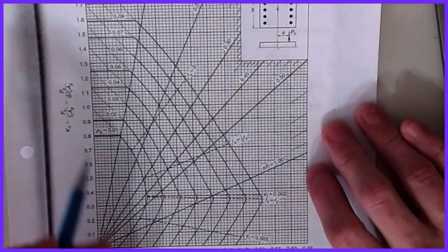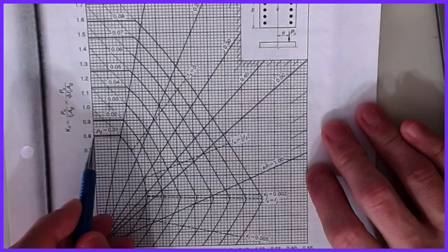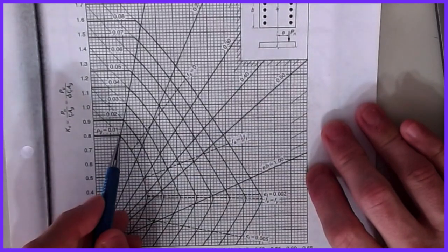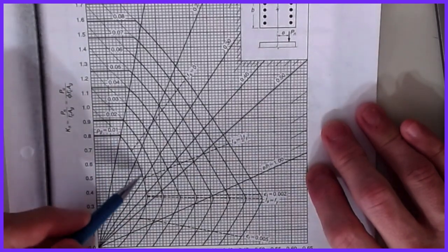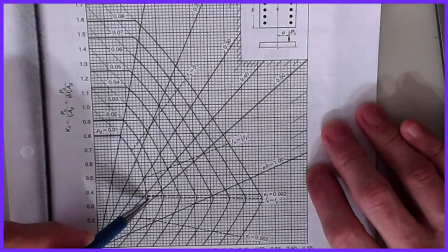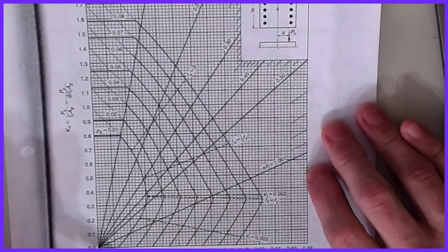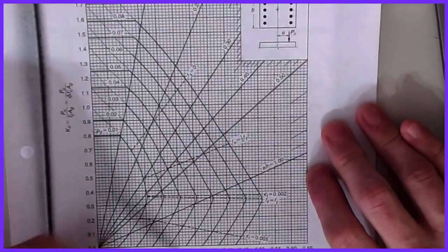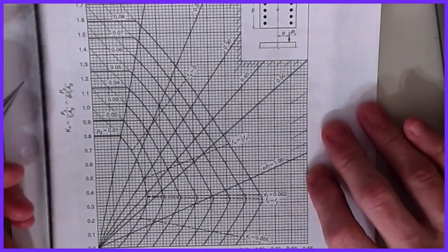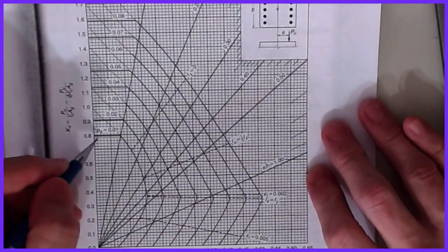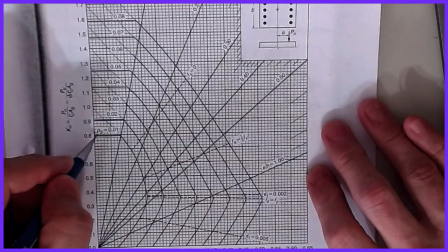interaction curves that you see. And you can see that basic shape that we talked about. Here's my P0 limit, and it comes over, and then it decreases down to some point. So rho balance for this one is about here, and then it comes back around here. And then there's another one; you get all these concentric rings almost that come around this thing. Each one of these rings represents a reinforcement ratio for the column.